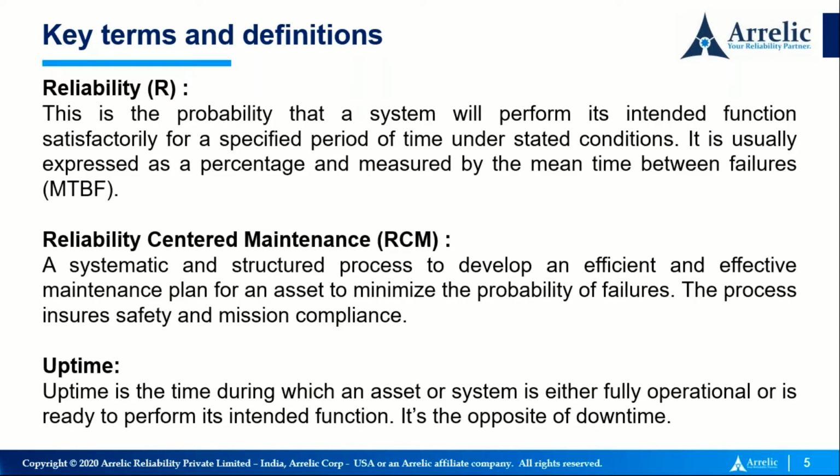Reliability, defined as the probability that a system will perform its intended function satisfactorily for a specified period of time under stated conditions. It is usually expressed as a percentage and measured by the mean time between failures. Reliability-centered maintenance, RCM.